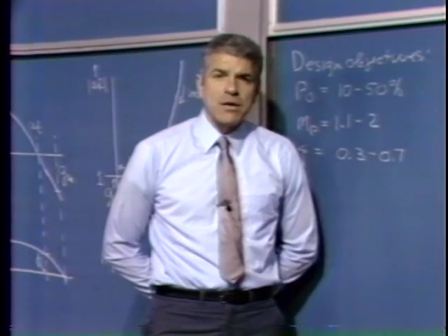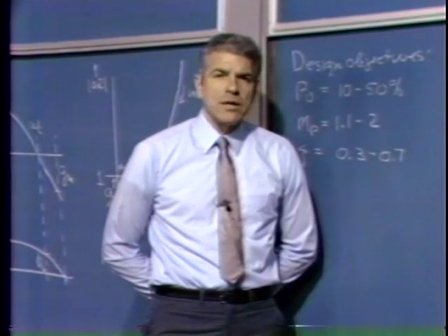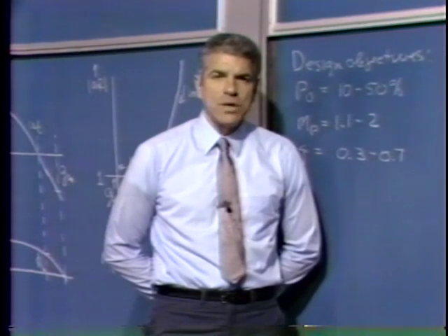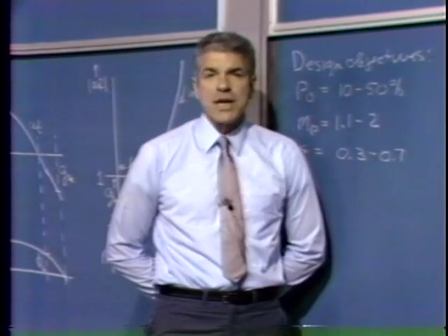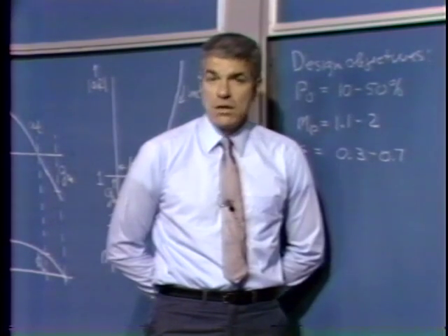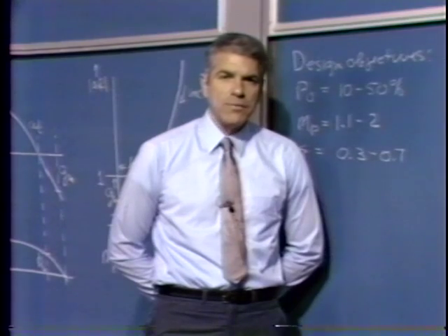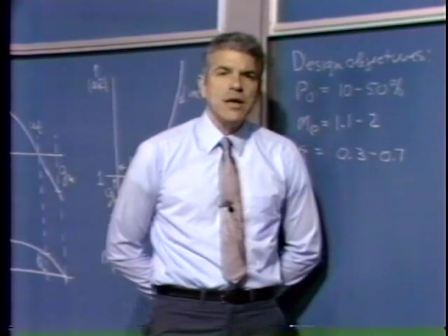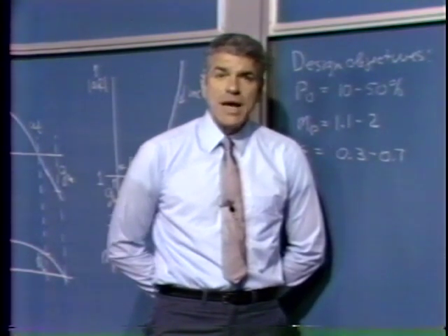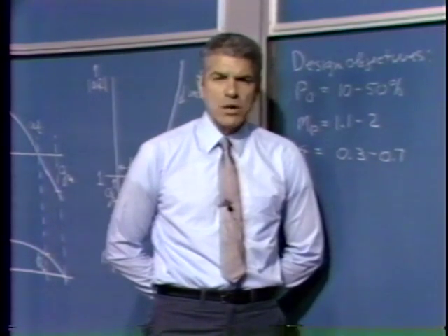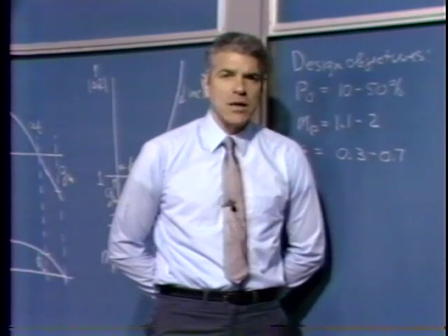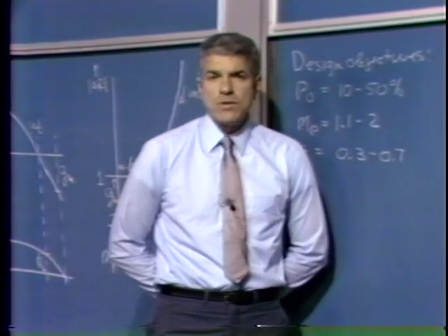For example, if we have a servo mechanism, a mechanical feedback system, where the critical frequencies associated with many of the elements in the loop are quite low, corresponding to mechanical frequencies, a few hertz in many cases. We're generally able to change the loop transmission magnitude at will electronically. If the signal exists in electrical form at some point, we can put in an amplifier that has a bandwidth so far in excess of the mechanical bandwidths that we don't add any additional poles, we don't change the phase characteristics of the loop transmission. We're able to simply modify the magnitude characteristics.